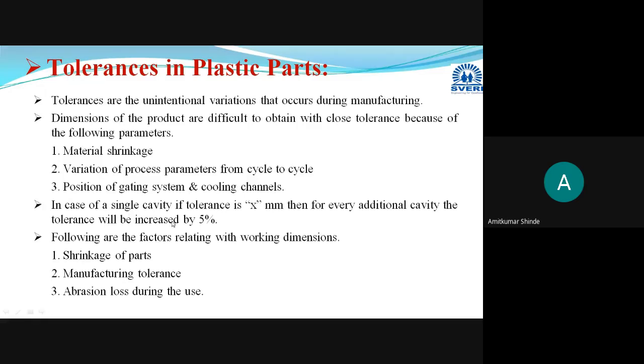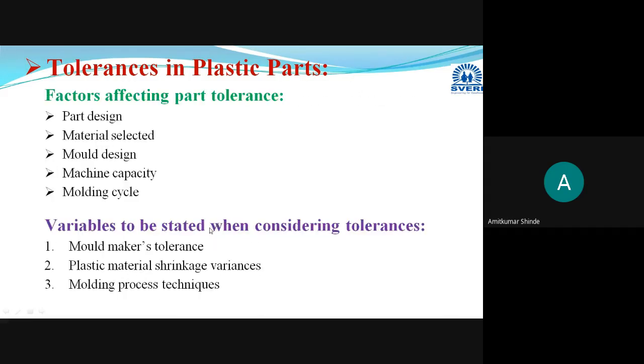Suppose you are using a single cavity mold, and the tolerance provided is x millimeter. Then for every additional cavity, the tolerance will be increased by 5% of x.